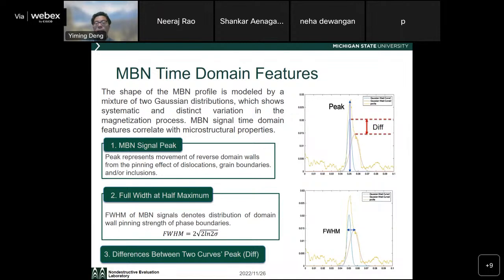For example, you can have Fourier domain data acquisition. Yesterday, we talked about an example when we do microwave imaging, and if you use a VNA, you can get frequency domain data acquisition directly by VNA frequency sweeping. Of course, you can get the data acquisition in other domains, depending on your sensing methods.